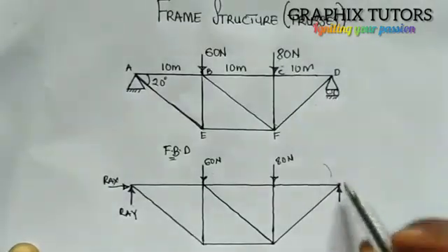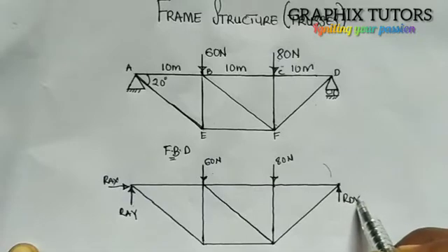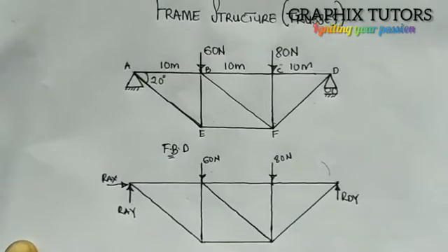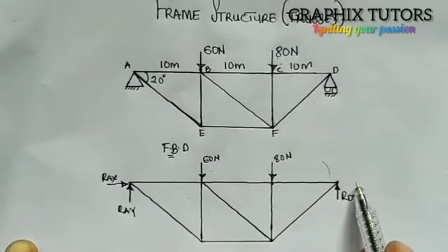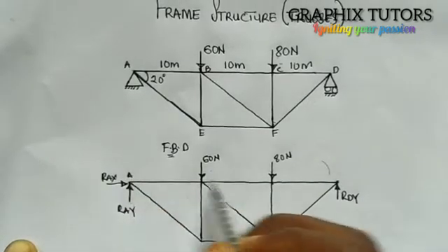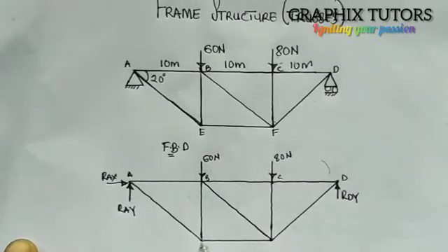Now this is a roller support. A roller support only has just one reaction, and that is what? Our arrow dy. So this is F. You see that the roller support just has one reaction, and this is at point A, point B, point C, point D, E, and what? F. So we've done the free body diagram, we have exposed all the reactions in the supports.